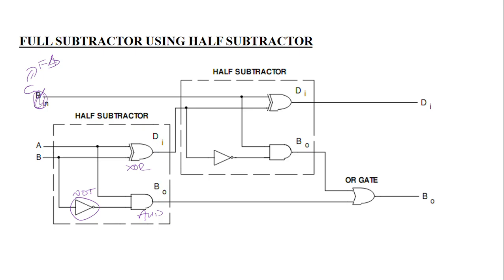When you subtract two bits, or more than one bit, the result of the subtraction is called the difference. While generating a carry it is called a borrow. In generating the borrow we use a NOT gate for the second input.